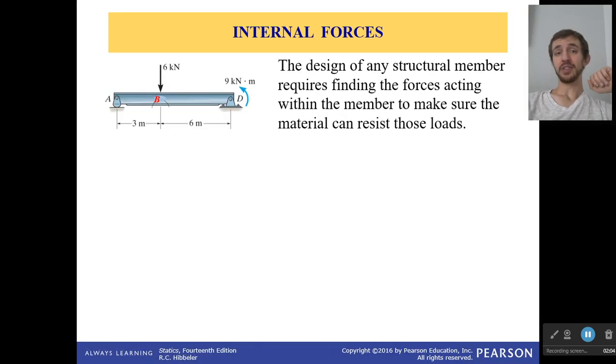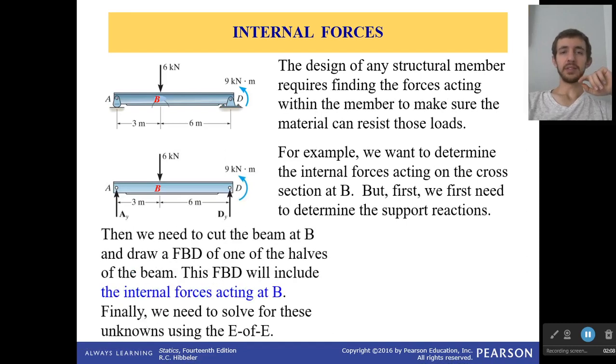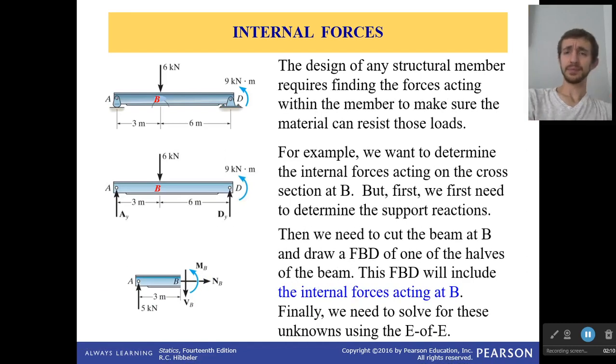So internal forces, what do I mean? When I say internal forces, I'm saying at a particular point in your beam, in your member, whatever it is, you're going to cut it, and you're going to figure out what the forces are inside of the member. Because there are forces inside this member that are constantly resisting the external forces, keeping it from moving.